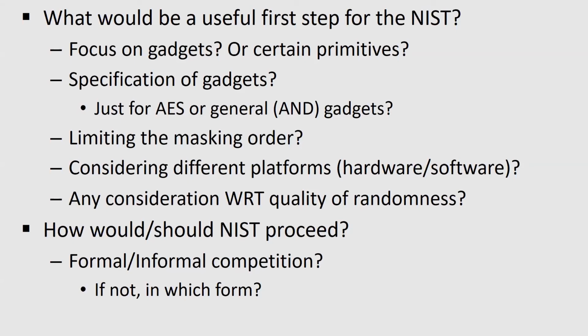But sort of like what the chip manufacturers do when they produce silicon, they don't test every wafer, but they do a statistical sample. They pick some end products, they measure their properties, and they make a judgment over the entire production line. And so I would assume that once you have done all the testing during the design phases of the product, and you've come up with a mask, then you go to the foundry, you produce the final chip, you have to do some kind of final product test to characterize it properly and report it in the same manner as I described before. So you have a consistent testing and reporting story to maintain in your company as archives, such that if somebody came and asked you what kind of testing you did, you can show the record and be able to reproduce parts of it per auditor instruction.